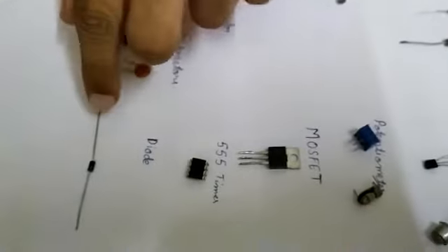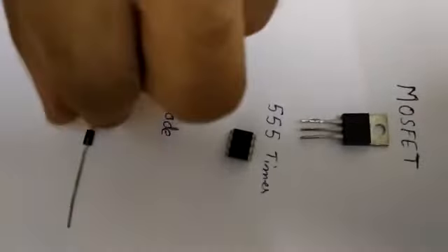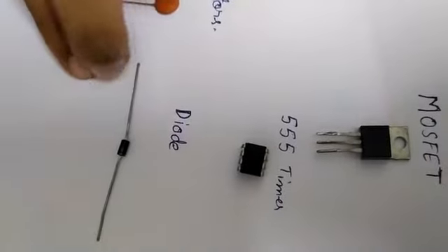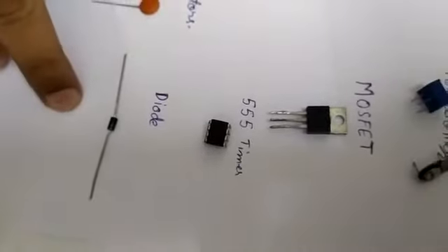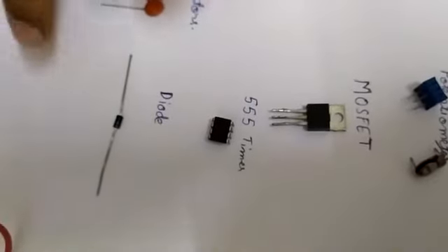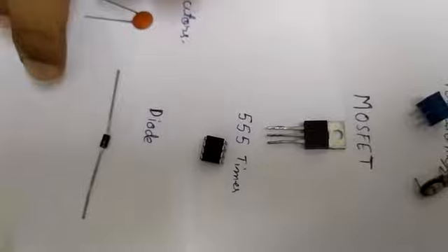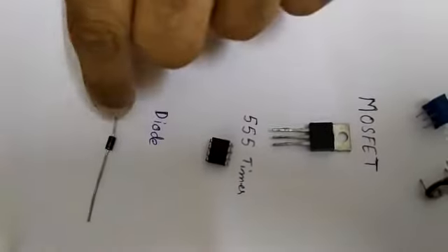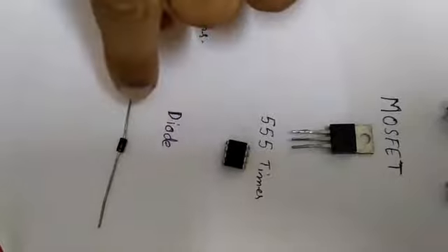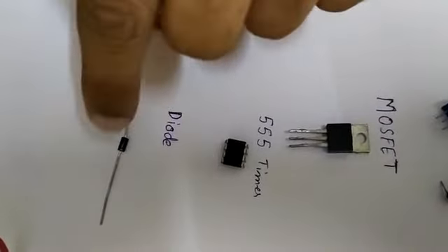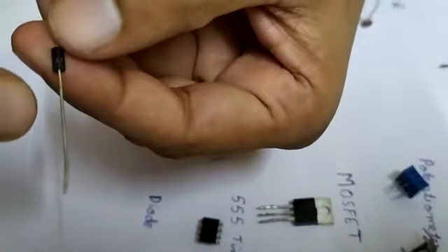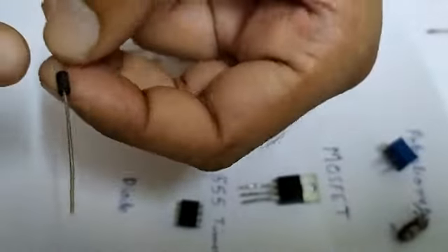Next we come to our last component, diode. Diode acts as a valve or a switch. It passes the current across it in forward bias and blocks the current in reverse bias. It has two terminals. One is positive and one is negative, means positive is anode and negative is cathode. We can recognize which one is positive leg and which is negative. Here is a gray color ring at the negative side of diode, and the other side is positive.